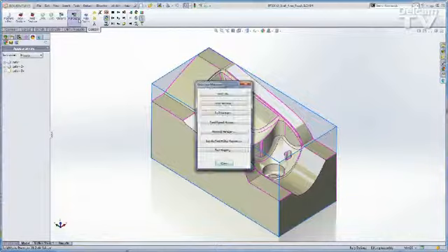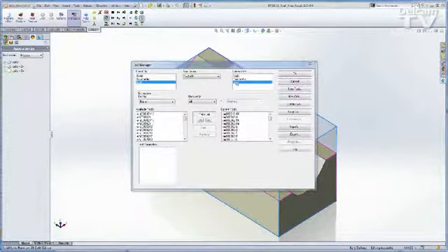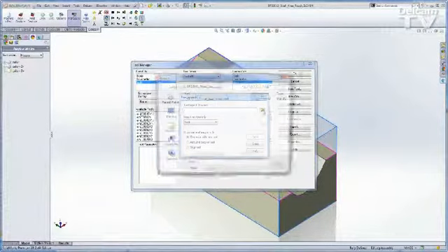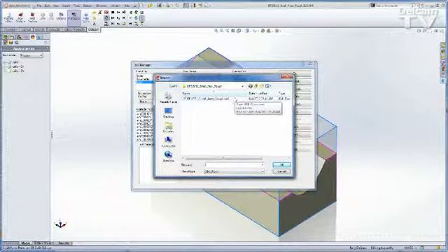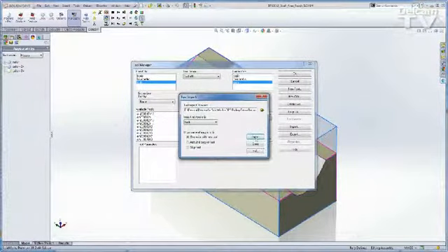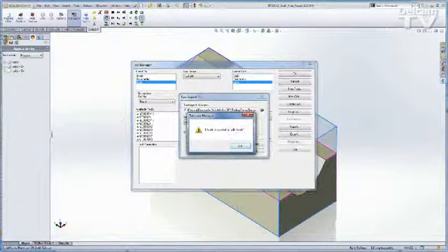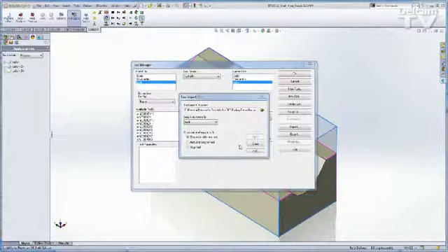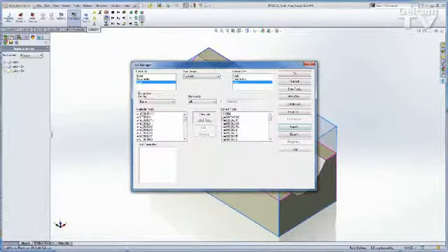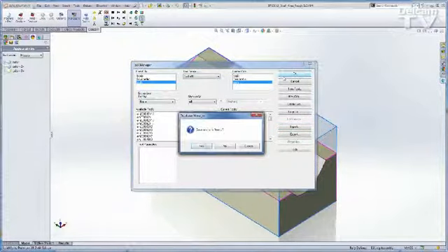So I'll go to Managers and go to my Tool Manager, and we're using the Tools crib. I'm going to import that tool crib. So I'm going to browse into my rolling demo to the small area rough folder where you have this small area rough.xml. Click OK and click import, and one tool is imported. Okay, that's this D32R6. So we're ready to go with this demo.